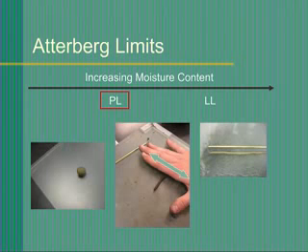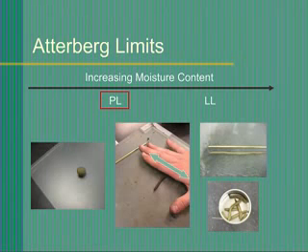When the soil reaches the plastic limit, put it into a pre-weighed sample tin and place the lid on the tin. Repeat this procedure with new balls of soil until you have accumulated 5 samples in the tin. Repeat the entire procedure over again so that you have 2 tins of soil at the plastic limit. Each tin should have 5 separate samples.